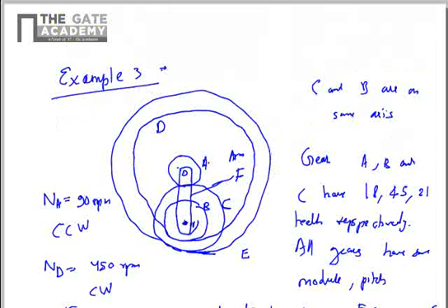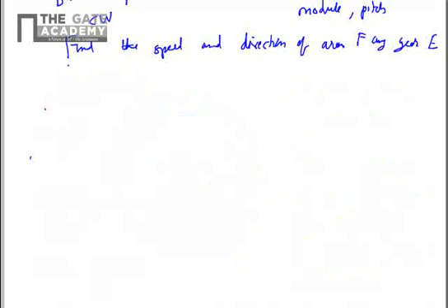We have to approach this problem in a systematic way, and it is not necessary to approach the problem in terms of angular velocity, since angular velocity is 2 pi n by 60, and 2 pi by 60 is anyway constant. We are working in terms of ratios, so we can work in terms of n as well. Now we have to solve this problem.